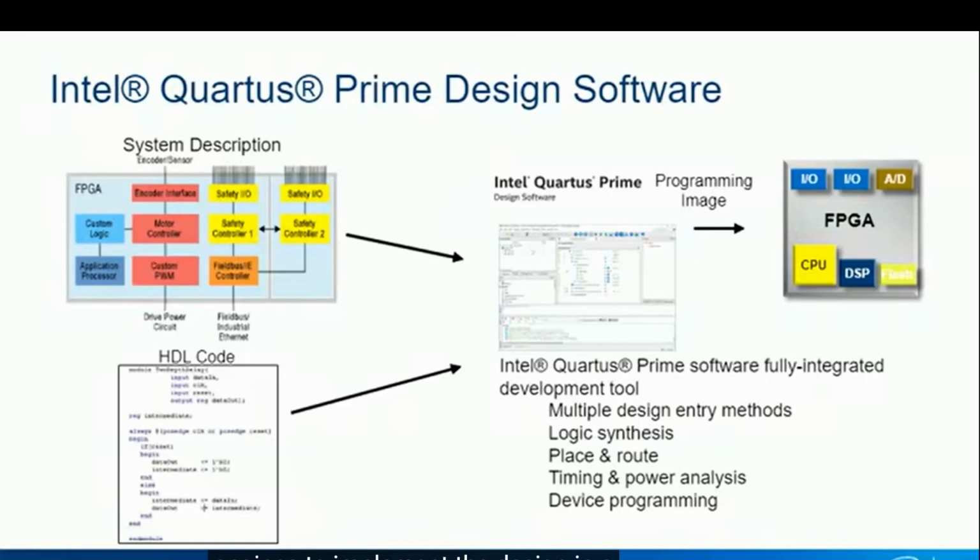The software includes a special edition of ModelSim called the ModelSim Intel FPGA Edition to perform simulation. It also includes tools to perform a static timing analysis, estimate device power usage, and program the device. As you've already seen, other features of the software, such as the Chip Planner, allow you to get detailed information about how a design is mapped to hardware in a target device.